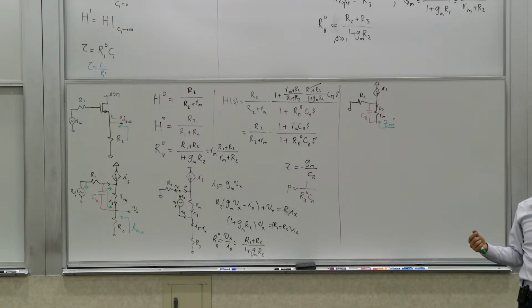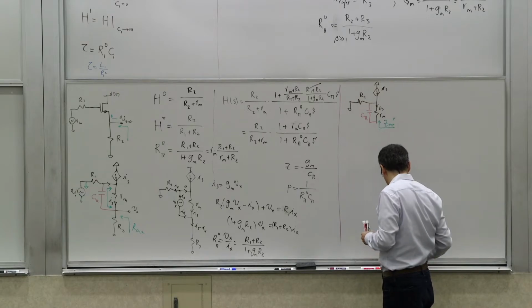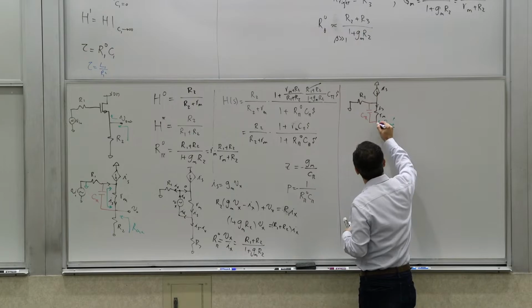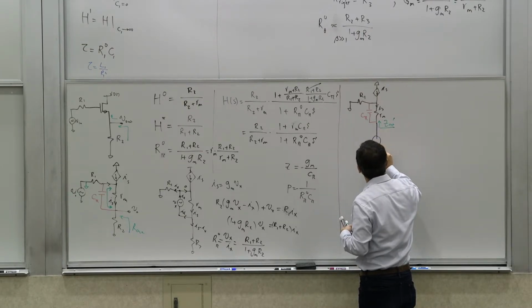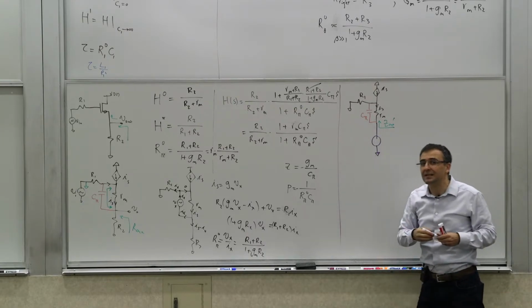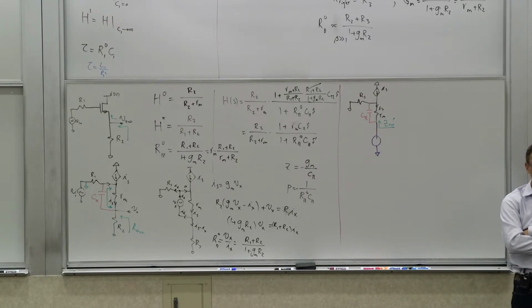So if you're trying to calculate an impedance, how are you really driving it? If that's the definition, how are we driving it? A current or voltage source specifically? If I'm trying to calculate an impedance, am I driving it with a current source or a voltage source? What is the impedance? The ratio of a voltage to a current, right? So the source, the stimulus, is the current. It's in the denominator, right? So it has to be a current source.